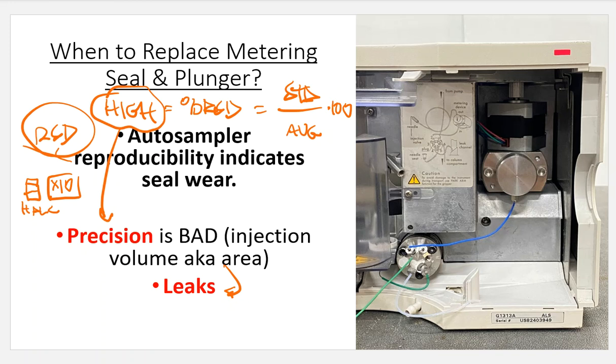They can come from the pump, they can come from the injection valve, but they can also come from the analytical head. And I don't want you to forget that idea, because there is a piston in there, there is a seal in there, and that is building this pressure up and injecting the sample amount. It should be the same sample amount over and over and over again. So that analytical seal is very important.